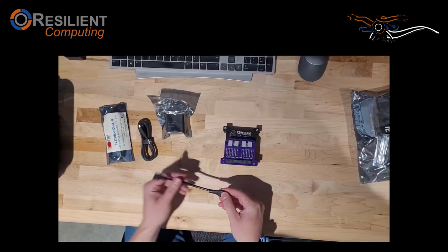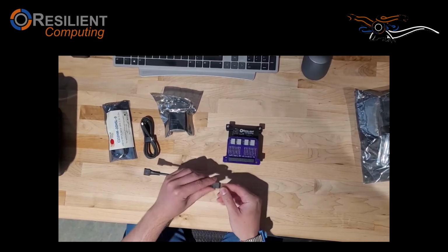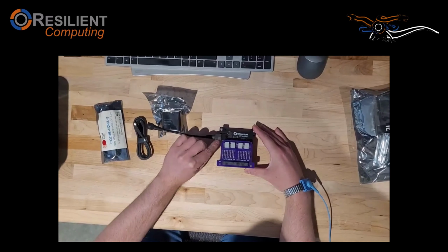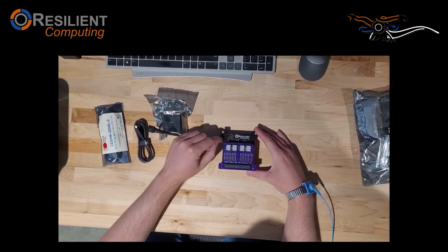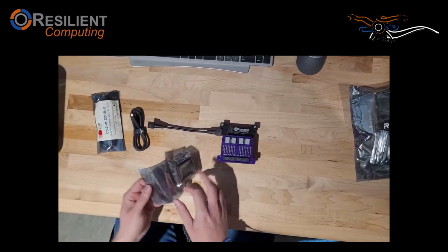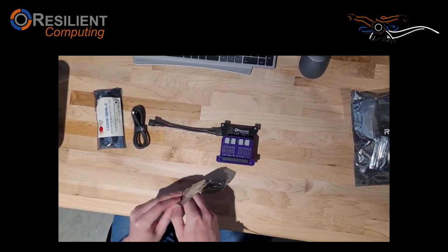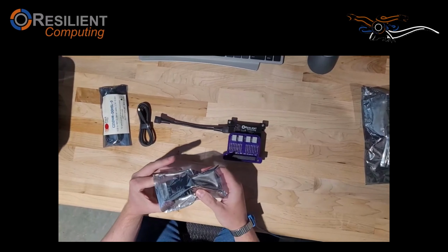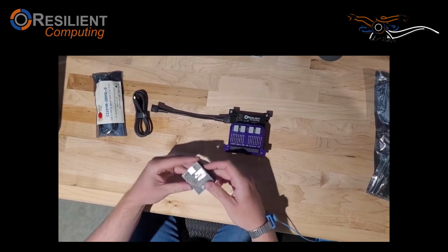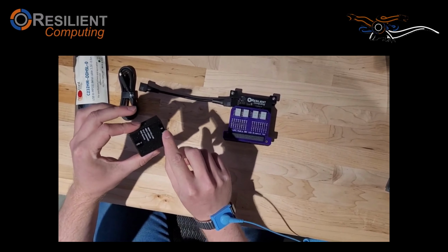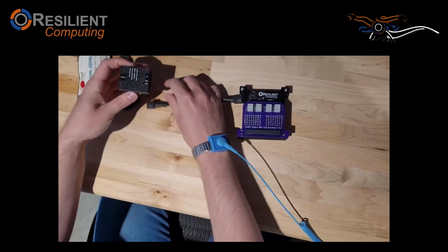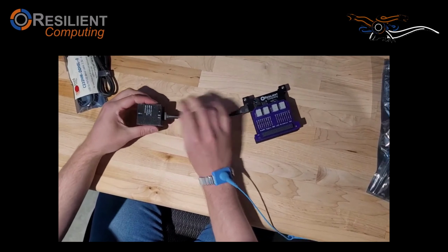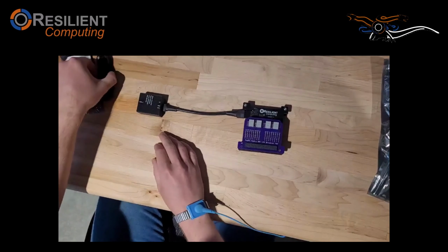Working out, the power and SPI cable will plug into the PMOD on the upper left-hand corner. Power will be the lowest pin, ground will be the next pin up. From there, you're going to go to the power puck. Marked, you're going to hook up I/O, ground, and VCC. Here, you will need to push fairly hard to get that in there. It's a fairly tight fit.